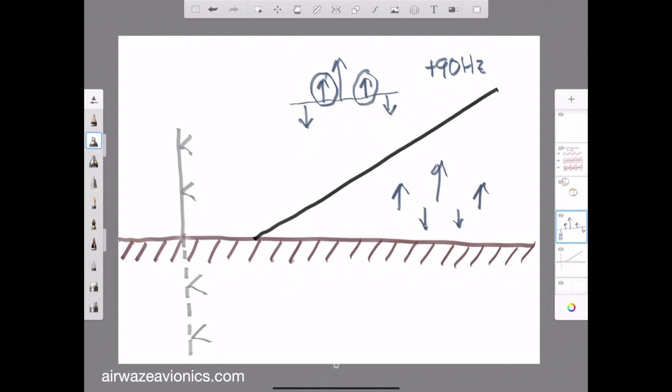So the end result is that there is an area of higher sideband power for 150 Hz below the desired glideslope. So it's higher 90 Hz above, higher 150 Hz below. The airborne glideslope receiver monitors and compares these levels. If the 90 Hz sideband power is greater, we know the aircraft is too high and you must descend. If the 150 Hz sideband power is greater, the aircraft is too low and you must stop descending or climb, as the case may be.